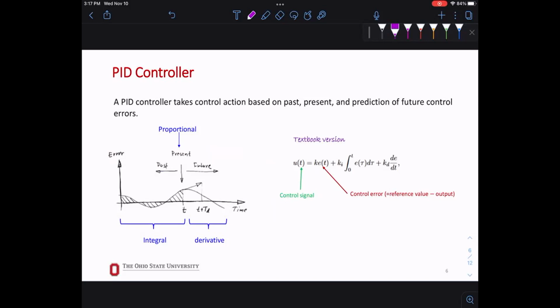In the open loop example that we had, the blue box that had a gain of 1/10, that's the P. A lot of times you just say gain, and you have gain scheduling. Proportional is enough for your system, but depending on where you are in the operation of your system, you might have to change that gain, but it can still be P. So gain scheduling can come from there. That's the P part. A lot of times in control applications, if the system is slow, P might be enough.